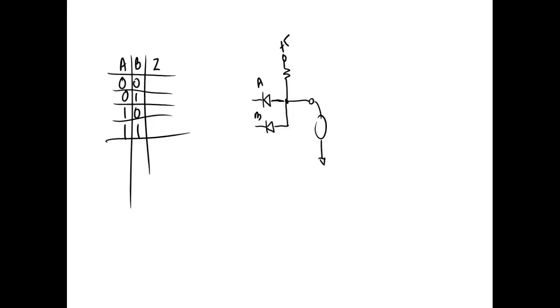Truth tables are okay as long as you're dealing with maybe up to 4 inputs. You start getting to 5 inputs, and you have 32 combinations in your truth table. With 6 inputs, you would have what, 64? So truth tables are okay with just a very few inputs, but they work well to show the operation of these gates. Okay, guys. So I'm going to come up here and put a 0 and a 0 right there. What would the output be?